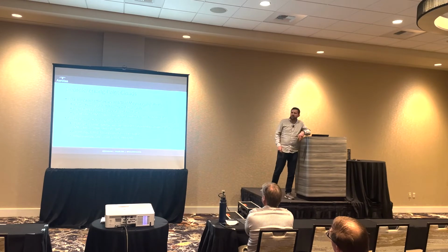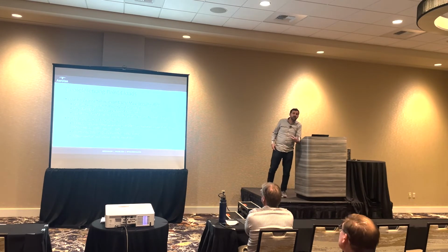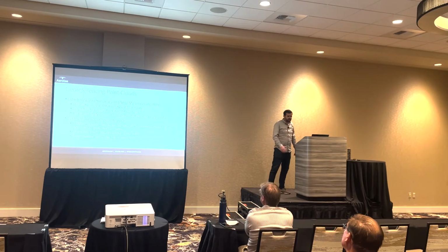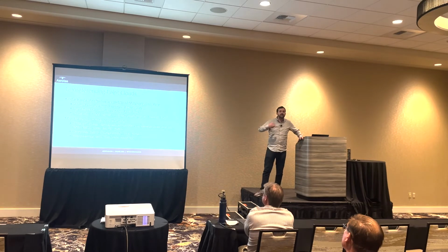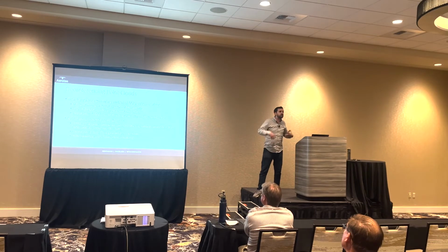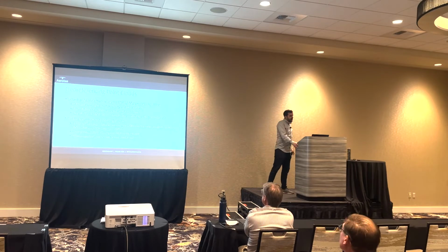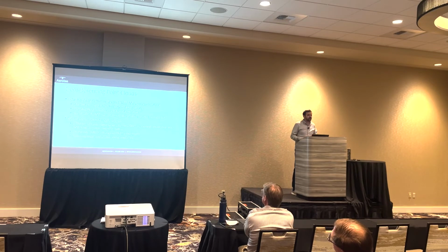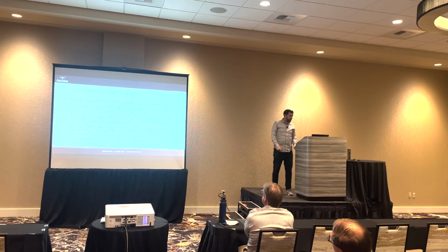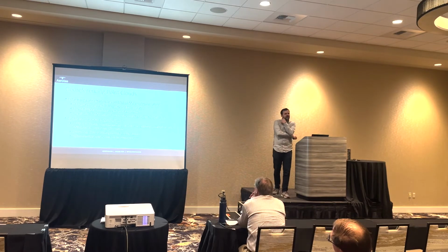The other reason that we like georeferencing is that LiDAR hardware relies very heavily on GNSS and IMU, and you also need to use check shots to verify your vertical accuracy. If anyone is interested in ASPRS positional accuracy standards, that's a way of measuring and even certifying the accuracy of LiDAR point clouds. You need to have check shots and ground data to do that. But having ground control points just provides so much other redundancy in case any other part fails. Like I said, using colorized point clouds, comparing LiDAR to photogrammetric data, and that blended photogrammetric workflow are all very helpful. So, any questions on georeferencing?